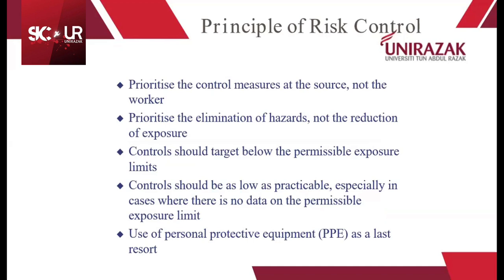Principle of risk control: prioritise the control measure at the source, not the worker. Prioritise the elimination of hazard, not the reduction of exposure. Control should target below the permissible exposure limits. Control should be as low as practicable, especially in the case where there is no data on the permissible exposure limit. Use personal protective equipment (PPE) as a last resort.